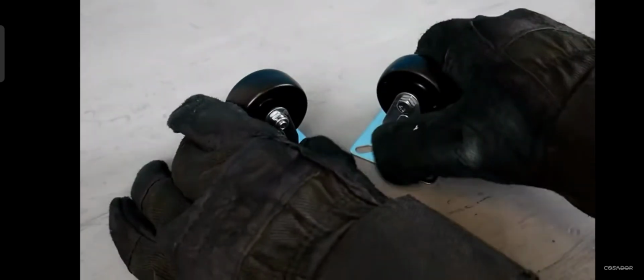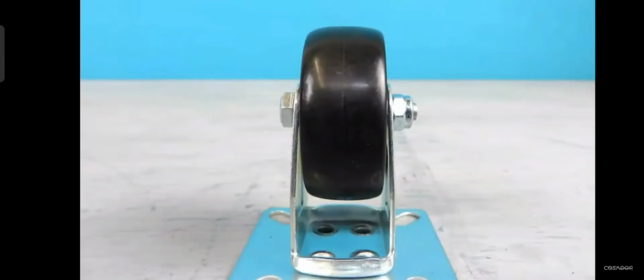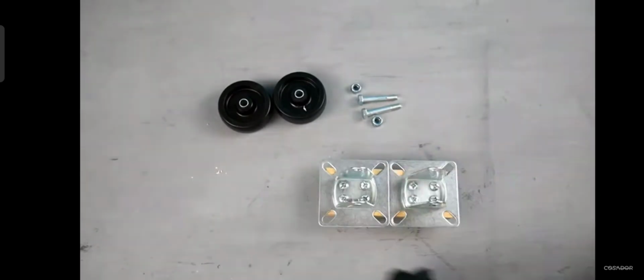Method number 4, with the roller. For this one, I need to make a tool. I need a couple of trolley wheels and a bit of timber. The trolley wheels should be plastic or hard rubber. They should be square on the edge and rounded in the middle for the best performance. And simply, I'll pre-drill and screw them to the timber in an inline configuration.